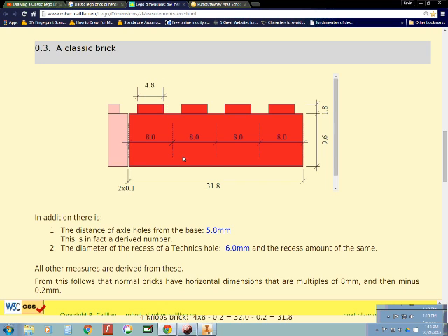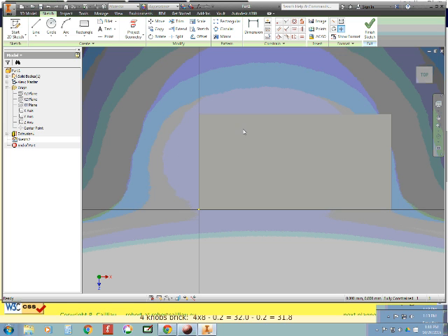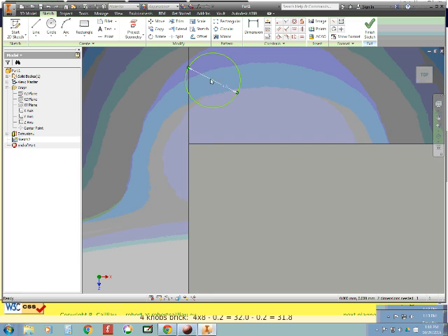It's 4.8 millimeters in diameter, and there's multiple ways to do this. I like drawing the circle kind of up here out of the way so it doesn't accidentally pick constraints for me. I don't want any constraints picked accidentally. So it's 4.8 millimeters in diameter. And now I can say, okay, I'm done drawing circles. I want to drag that circle down roughly where it needs to go, and I'll grab by the center point. There we go, and pull it down here.